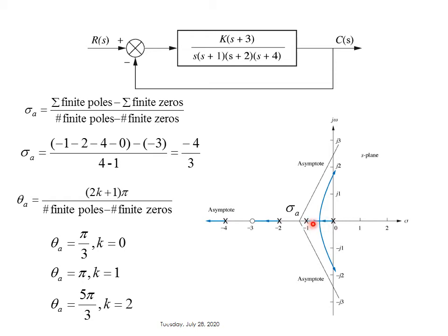So the -1 and 0 poles, like in one of our previous exercises, will go to a center point, meet there, and split into 2 directions, one towards positive j omega and the other towards negative j omega. One goes on the upper side and the other on the lower side. The part on top will go closer and closer towards the asymptotic line.